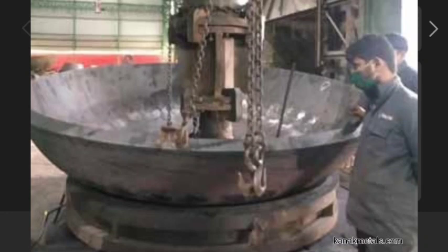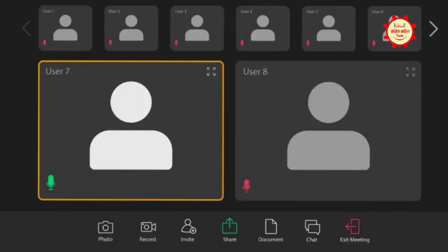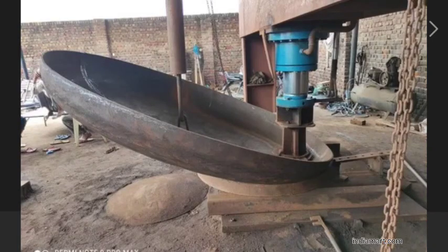If the person is very experienced, the deformation will be very little, and he will exactly form that crown within a few punches. But if the person is non-experienced or less experienced, he requires more punches, so accordingly the plate length is also required more. So it depends on who does the crowning activity, and you have to consider that person.